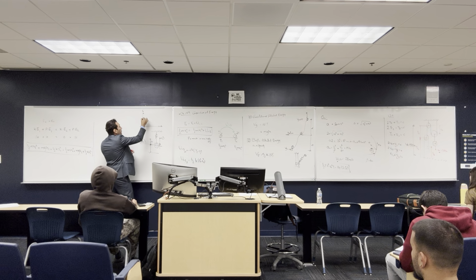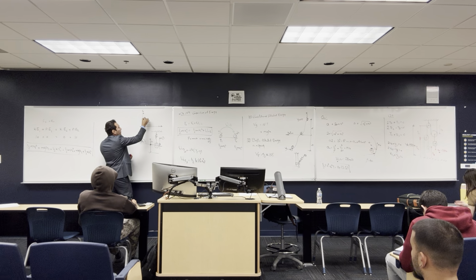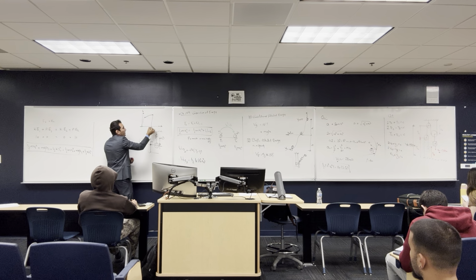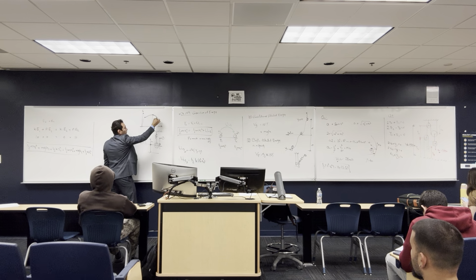But once you get past this point, the material can take more deformation, and the curve goes something like this, all the way to the maximum. There is no way to go back. Once you remove the load, the delta is going to stay there. That's a permanent deformation that is going to happen.